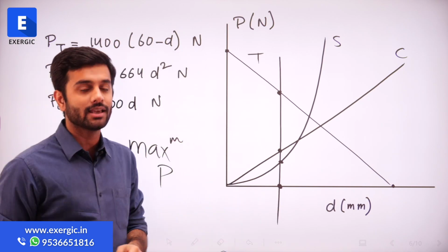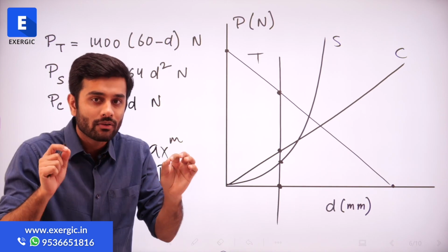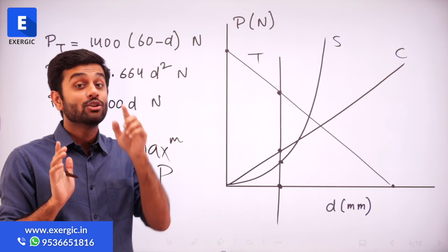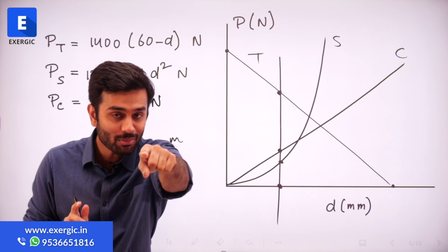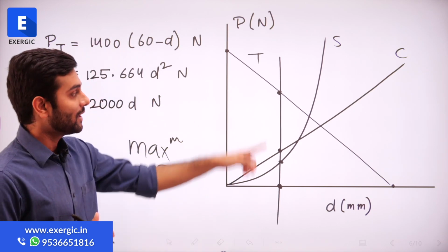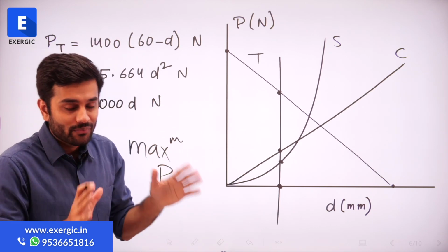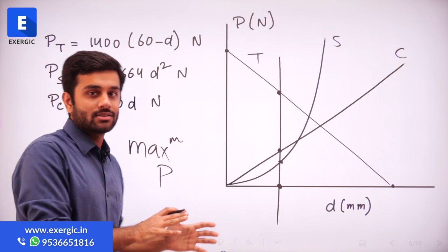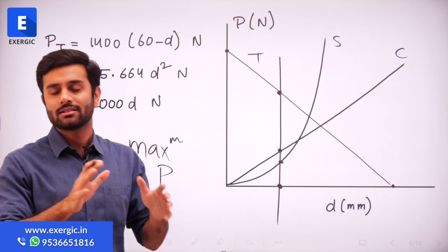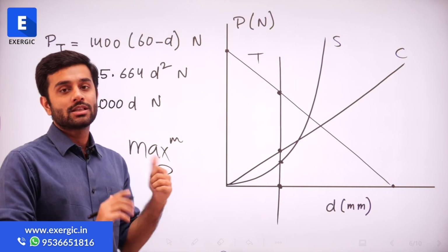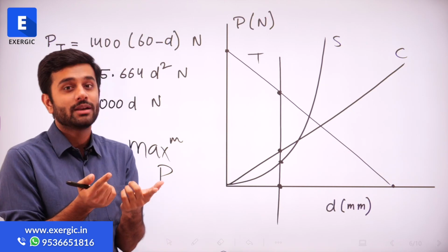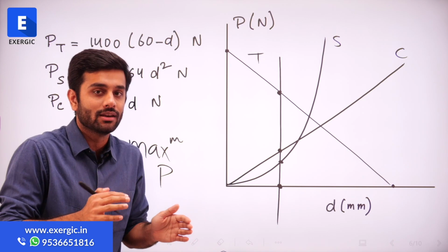And when the question was asking what is the maximum allowable value of P, then you were picking the minimum of them, not the maximum. In the discussion of strength of material, design and other such subjects, when we discuss maximum allowable value, it means it should satisfy other values as well, right?